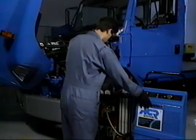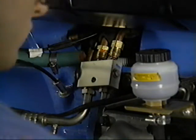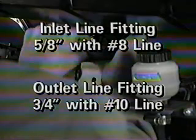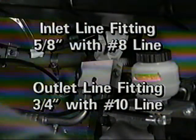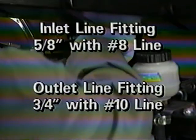When removing the AC evaporator coil, begin by discharging the refrigerant system. Disconnect the refrigerant lines from the expansion valve and immediately plug the ports. Note that the coil features brazed copper lines that go through the firewall. At the expansion valve, the inlet line fitting is 5/8 of an inch with number 8 line. The outlet fitting is 3/4 of an inch with number 10 line.